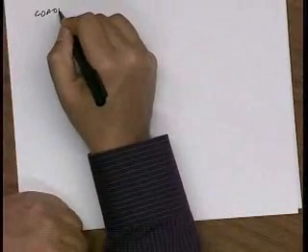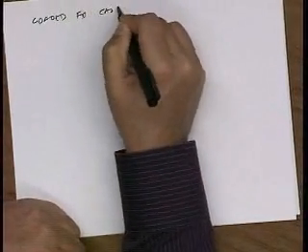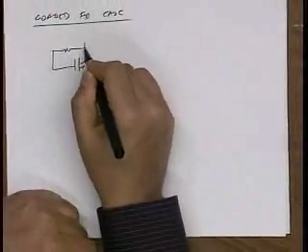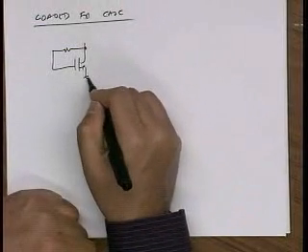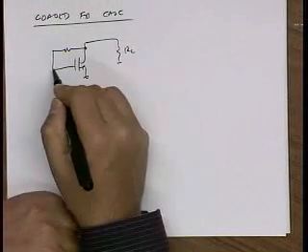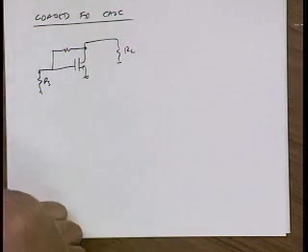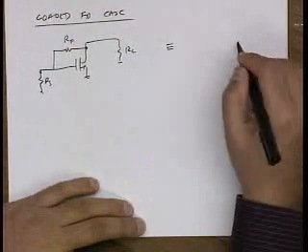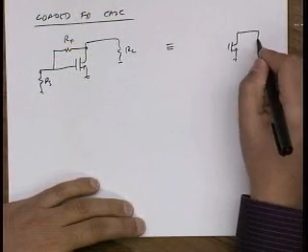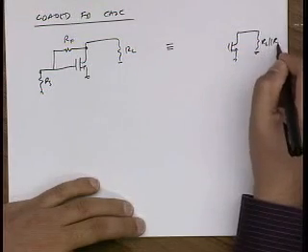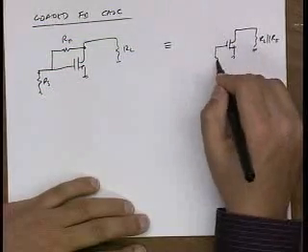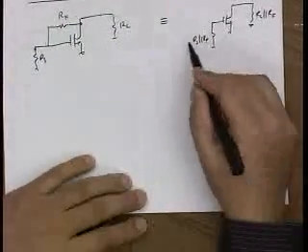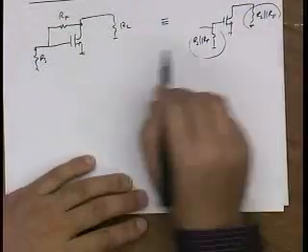So there's this, I don't know what to call it, I'll call it the loaded feedback calculation, where we take our original amplifier, again driving RL and driven by RS, and we say, okay, this is equivalent to an open loop amplifier loaded by RL in parallel with RF and RS in parallel with RF. Okay, and we're going to talk about how you know they're in parallel.